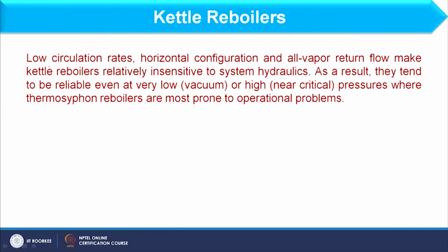So, these are some points about the kettle reboiler. Let us have more discussion about this, okay. So, it has low circulation rates, and the horizontal configuration and all-vapor return flow make the kettle reboiler relatively insensitive to system hydraulics, okay.